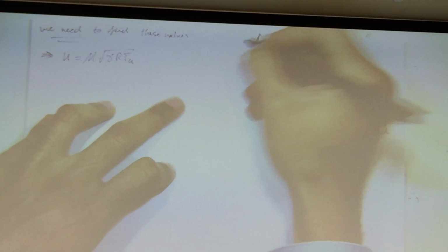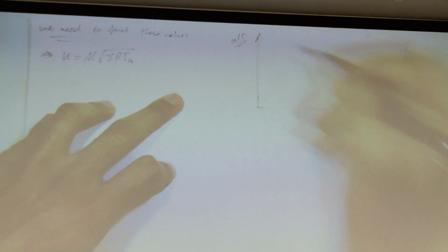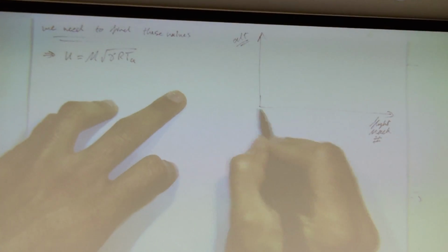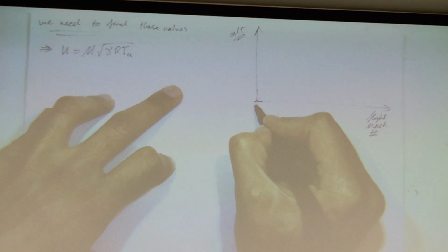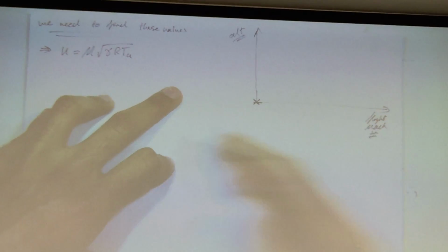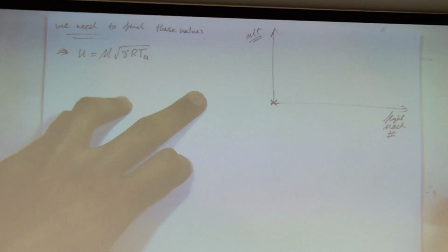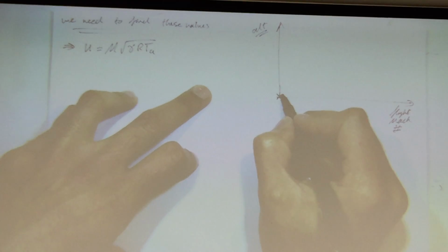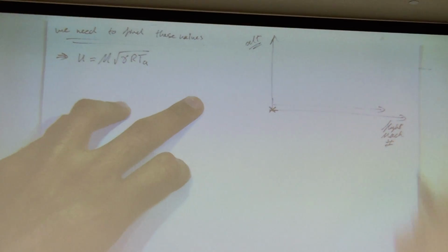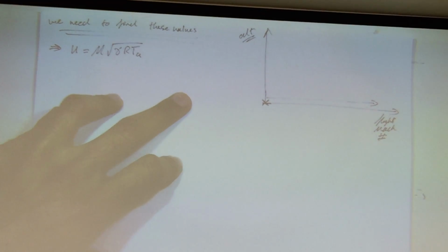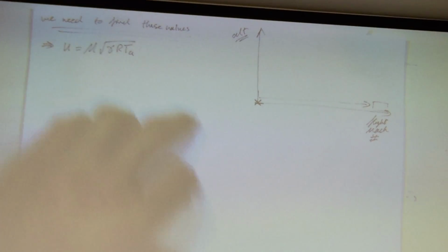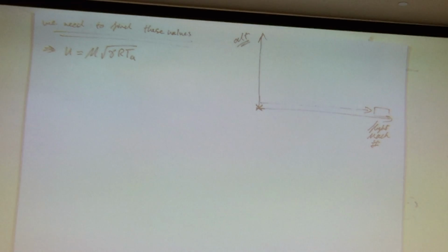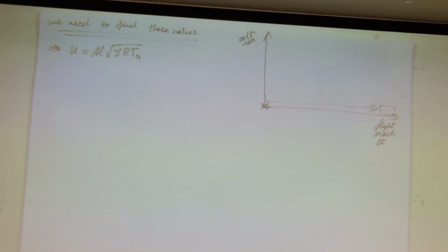And this is altitude. Depending on where you're at, this is ground level, sea level static, right here. You're not flying, the flight Mach number is 0. And sea level RAM is when you're right here, at the same level as the sea level, ground level, but you're ramming at really high Mach number. That's when you're going to air shows and your aircraft are very close to you. That's that condition.